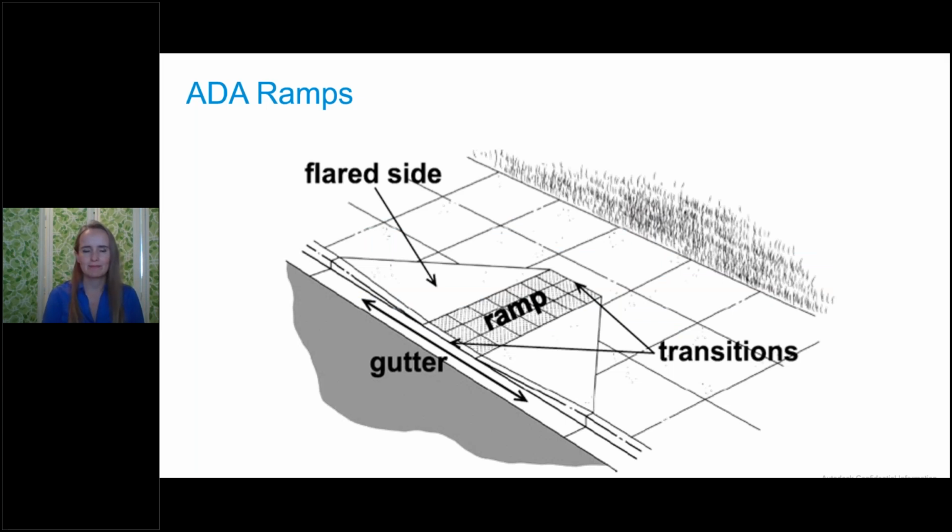Primarily, when I'm doing corridors, it's for the curb for a parking lot and maybe for the sidewalk. But when I'm doing the ramps, I will create a normal curb section assembly for all my curbs, and then create a little ribbon curb assembly for the transition along the gutter line.